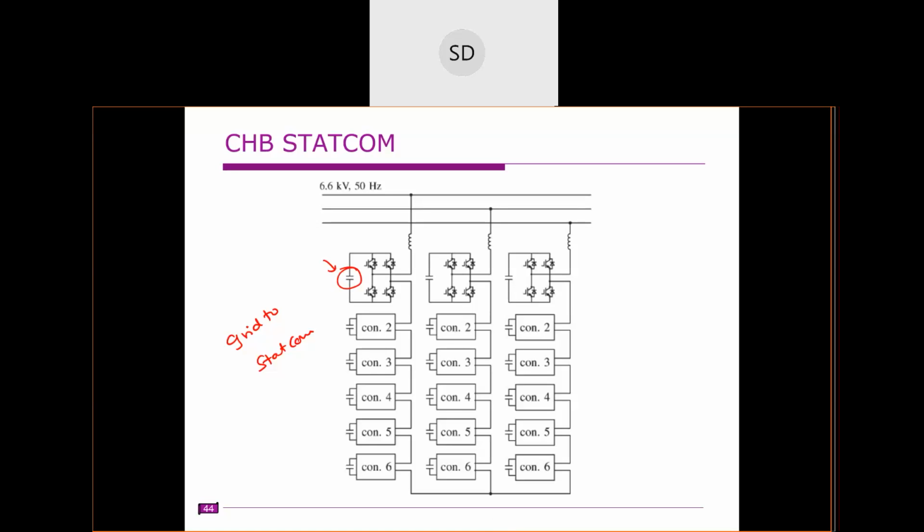Okay, so you got the point, right? STATCOMs are ideally designed to transfer the reactive power, but the inverter in the STATCOM produces conduction and switching losses. If these losses are obtained from the energy stored in the capacitors, the capacitor voltage will be reduced. When the capacitor voltage reduces, the performance will be affected.